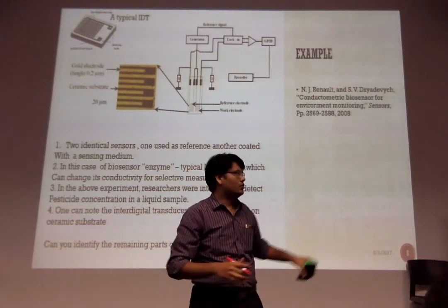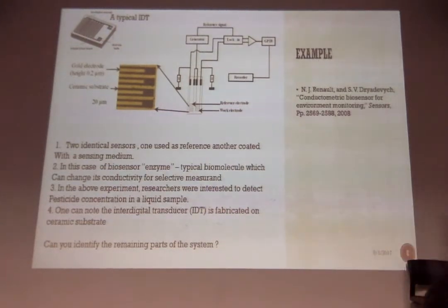Yeah? So to measure this change in resistance, change in impedance, probably one can think of a circuit. Something like a signal generator is there, and the sensor, which is having some change in impedance, can be connected, so there is a load resistance. Using a simple potential divider circuit, I can now measure the change of this. Yeah? Why do you think I should connect a signal generator, an AC signal?